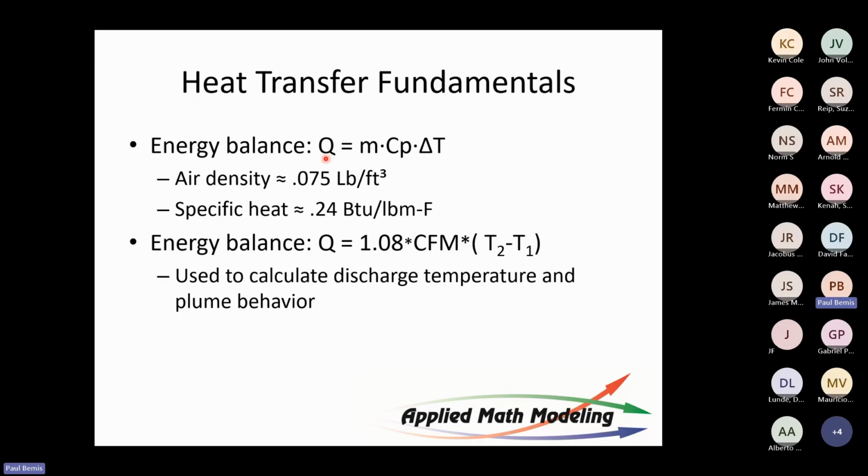The heat is equal to the mass flow rate times the specific heat times delta T. Delta T is inlet outlet temp. This is the T2, T1. So here, I'm looking at atmospheric outside temp here, and this is inlet temp. So it's the delta T times the mass flow rate, which is defined by the fans, times the specific heat, which I've shown as a constant, which is not a constant, as it turns out, because as temperature rises, the density changes, this number will vary.